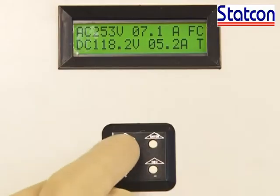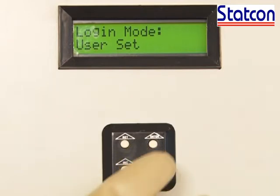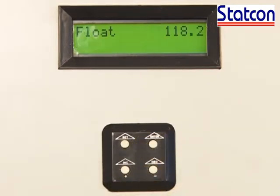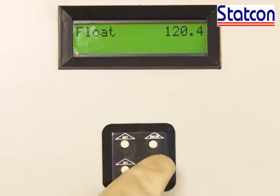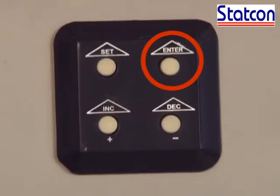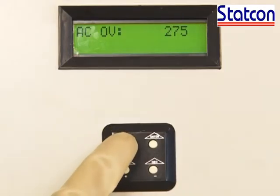To adjust, first we have to select user setting by pressing the set key. After that, we have to press the enter key. To go into the setting, we can increase the displayed parameter by pressing the increase key and can also decrease it by pressing the decrease key. To set the adjusted value, finally, we have to press the enter key. To adjust another parameter, we can follow the same steps and can access the next parameter by pressing the set key.